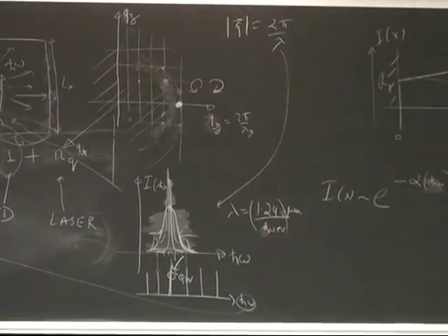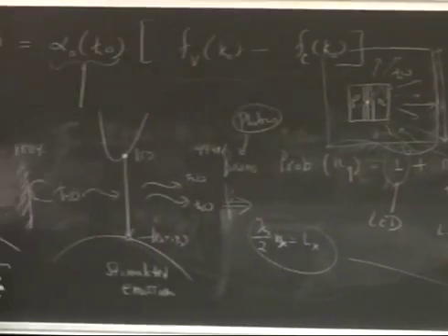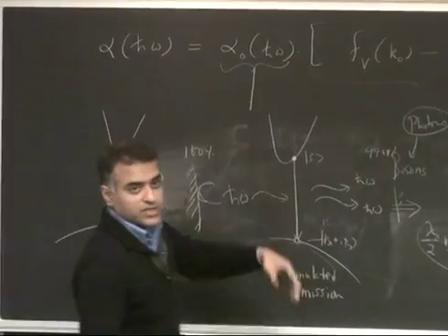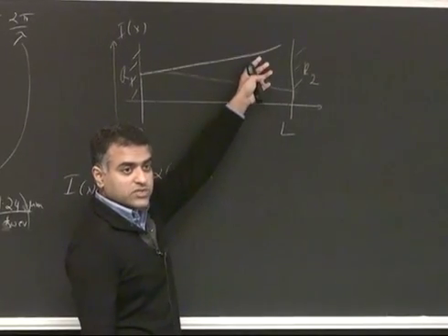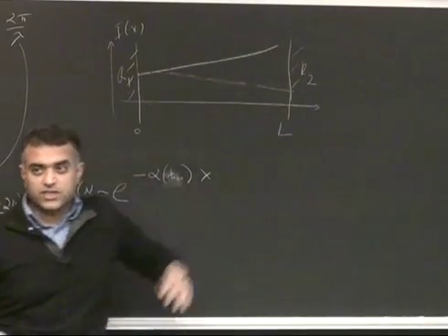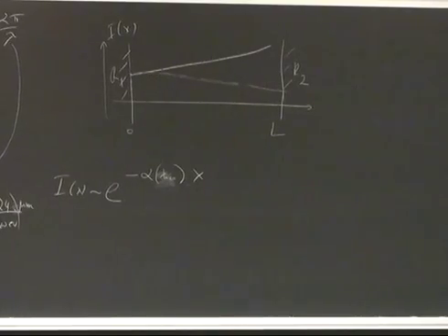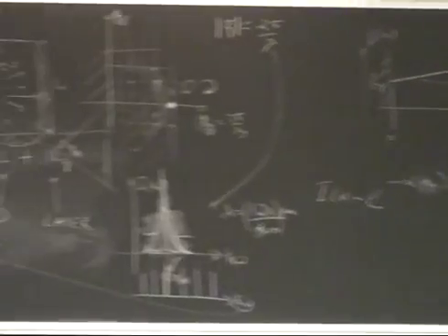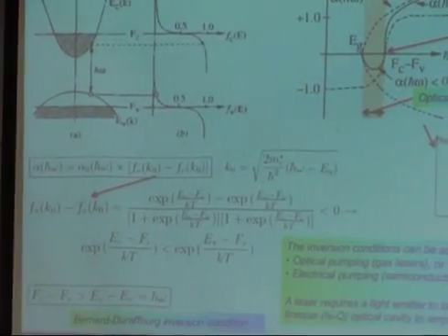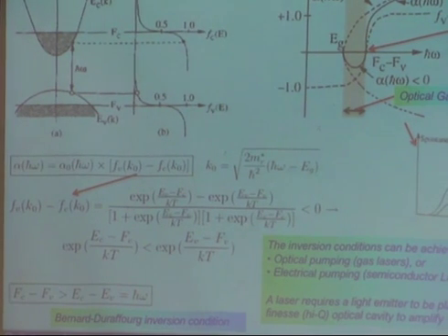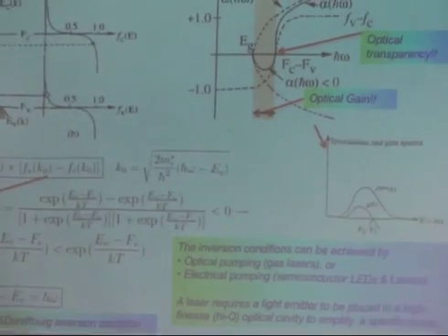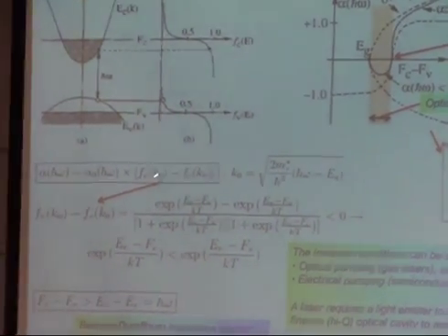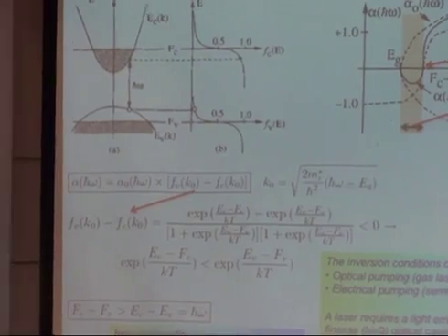Okay, but let's look at the absorption coefficient a little bit more now, because that's the gain, the critical element, right? You can make your material as pure as you like, and then you'll be stuck with that. Now the game is to increase the absorption coefficient so that you overcome the losses, right? So this term, the non-equilibrium part, is really the knob that you can turn to make your absorption coefficient higher. Let's look at what this term is.